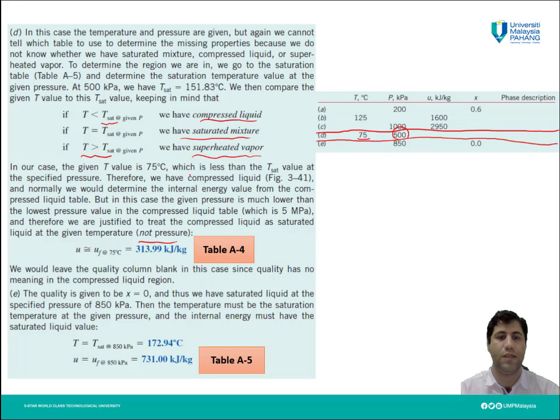What we found in the table is 151.83 degrees Celsius, which is obviously higher than our temperature. And it means what we have here is compressed liquid.